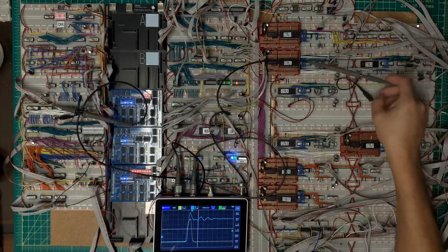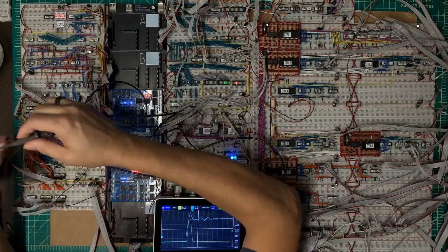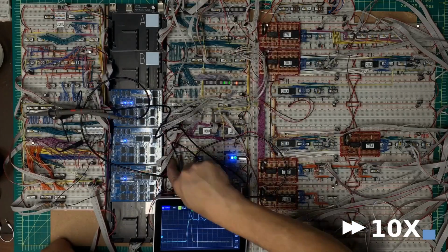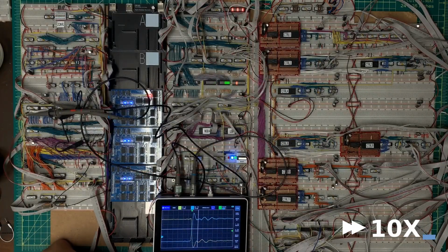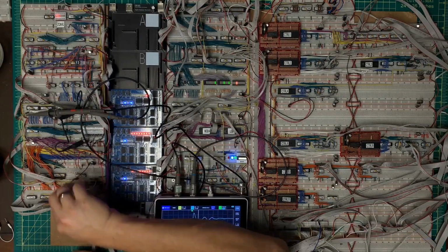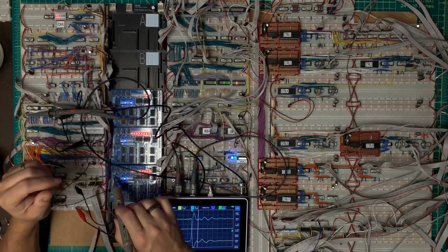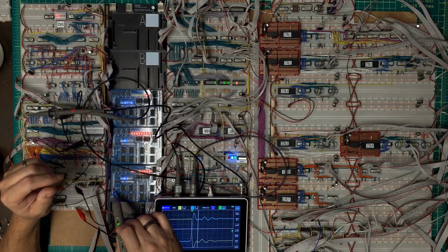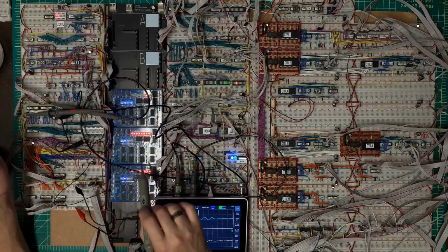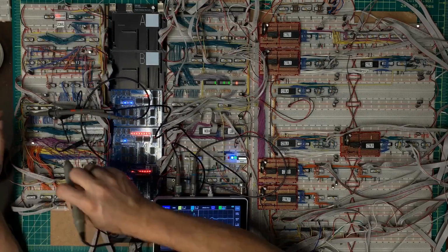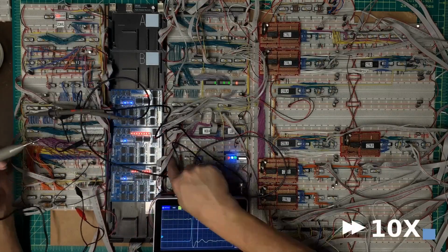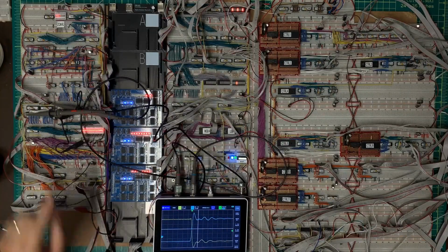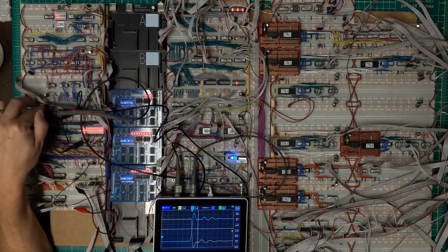Okay, let me come back over here with this. So that's the latch, that's output enable. So the question is now, what's on the main bus? 0, 0, 0, 0. So I did not latch. So that is working properly there. I did not latch a good value. Okay, so my latch is happening too early.